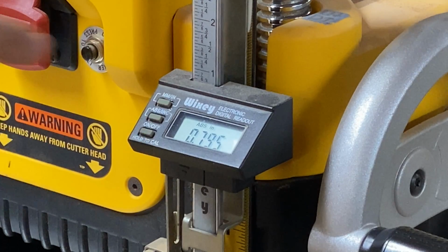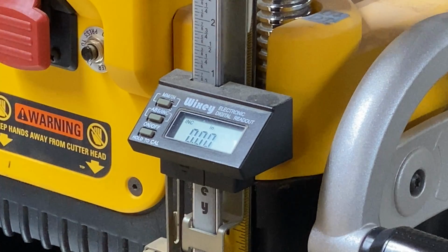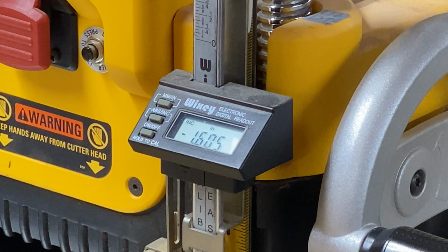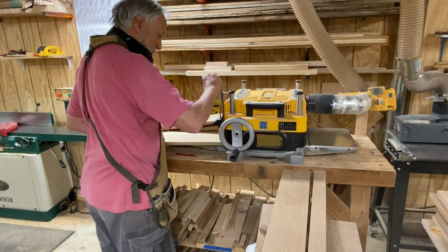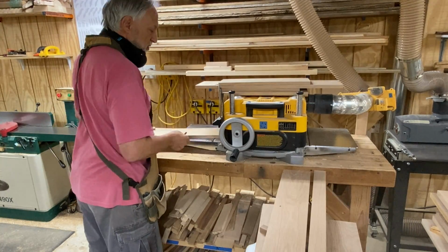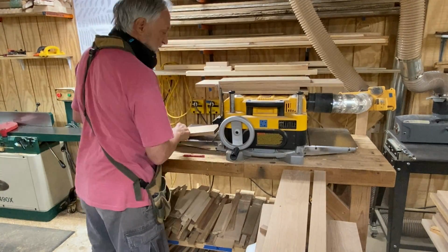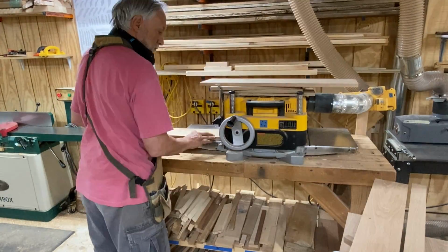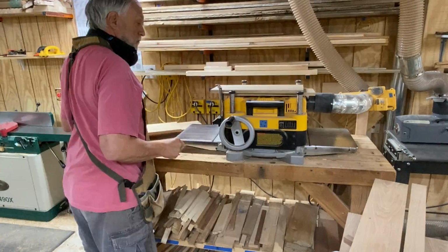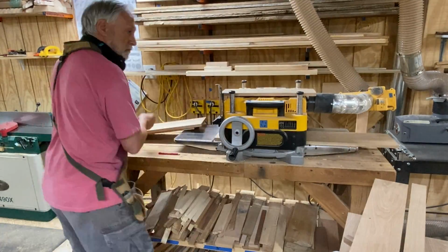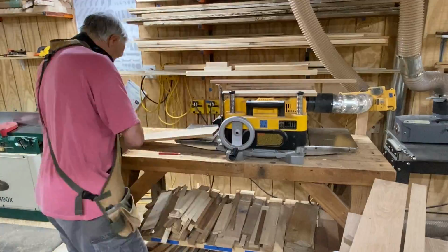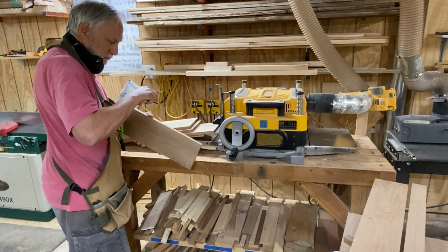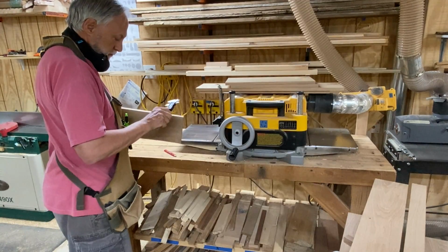Another great add-on to any lunchbox type planer is a Wixie digital gauge. It allows you to make repeatable cuts down to 1/1000th of an inch. It's invaluable when you are trying to get all your boards down to the same thickness, as I am here. Just measure the thickness of each board and write it on the board. Then send the boards through starting with the thickest one and continue to run them all through as you get down to your rough or final thickness.